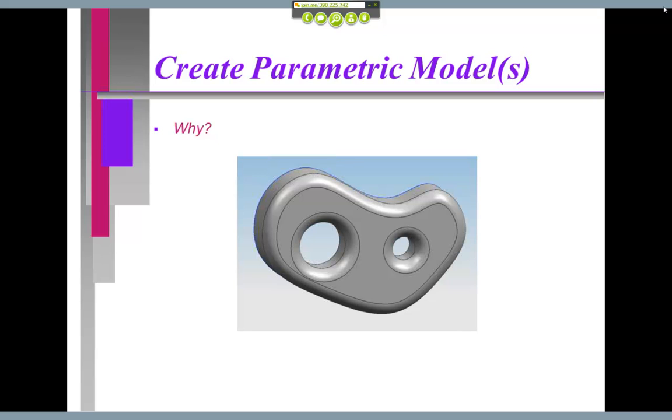There wasn't this concept of parametrics. Generally, once you made the mesh and went to solve this thing, you had to literally throw away the mesh, adjust the model, and then rebuild the mesh. In today's world, the mesh is associative, it's connected with the model. So if the model gets tweaked, it gets adjusted in length, it gets adjusted in thickness, generally the mesh will update and refine itself. So, good point.